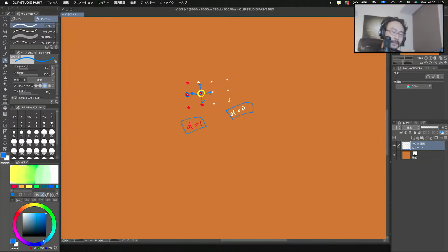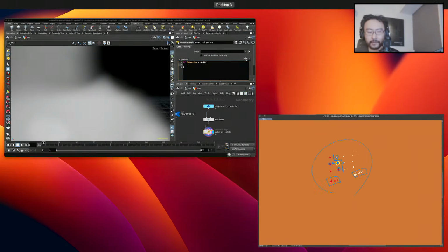But if the density is different between this one and this one, then you should have a surface or a threshold wall in between those 2 points, which is going to be used as a voxel surface. Same for this one. And for this point, you're going to have a wall here and so on. So that's what I would like to do as a volume wrangle.